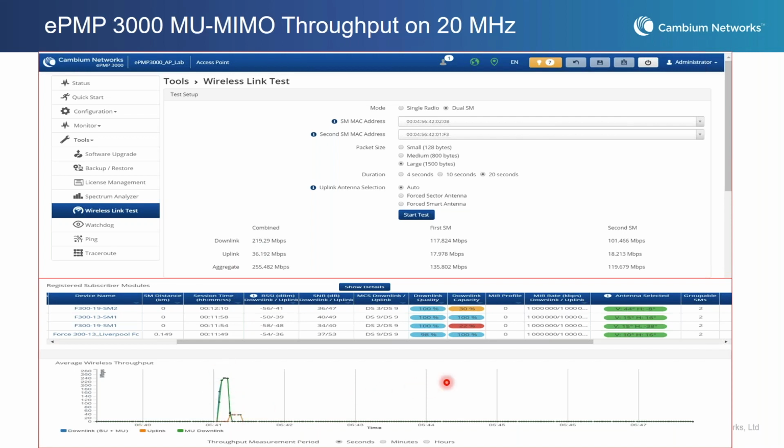And what you are seeing here, the antenna, is the smart antenna that does beamforming. Beamforming works by narrowing the beam from your traditional 90-degree sector to a smaller angle, which makes it steer away from the source of interference and increases your link budget.